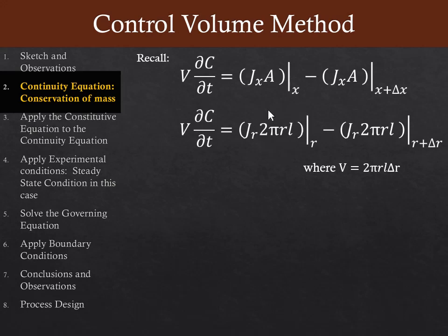This is just the surface area of a cylinder, right? And it's just located at 2 positions. So the inner surface, this R value is going to be different than the R in here, which is going to be at an R plus delta R position. All right. So we have to keep the R's in here when we're doing the evaluation in our next step, and we write this as a differential equation. But the 2 pi and L are constants, so we could pull those out.